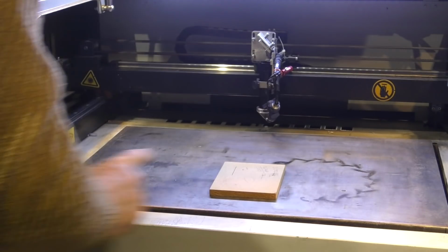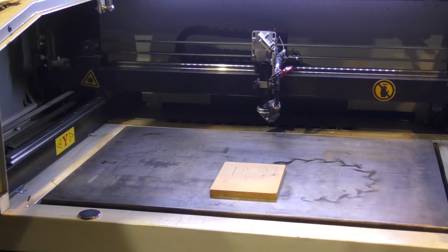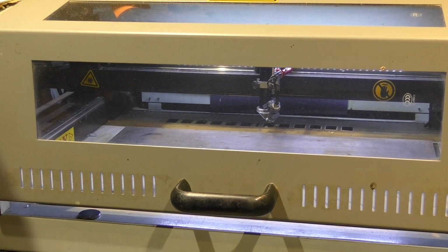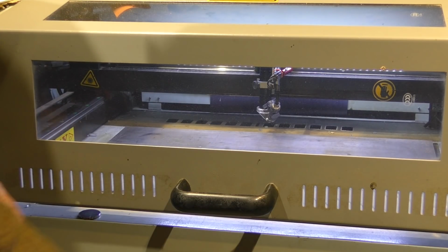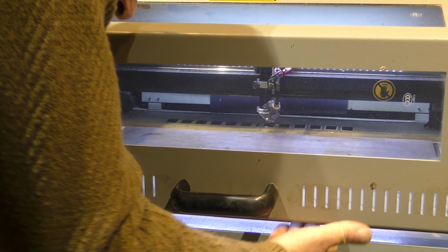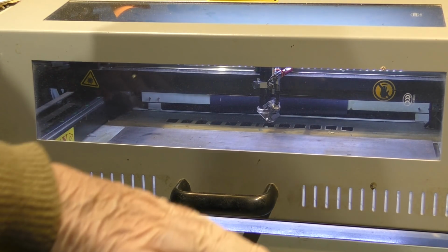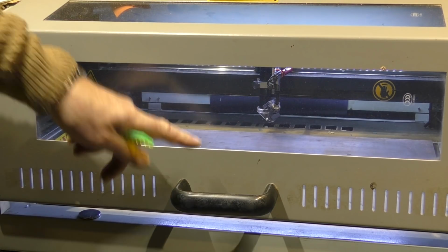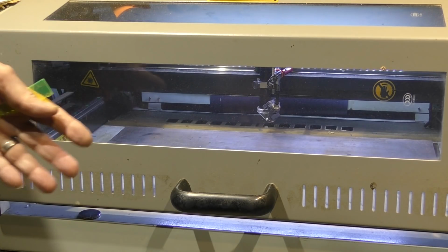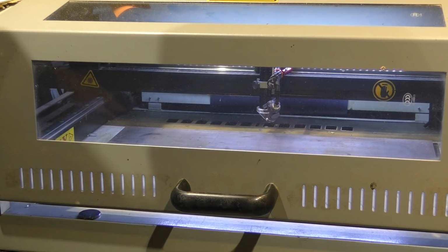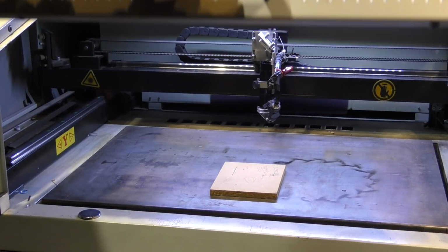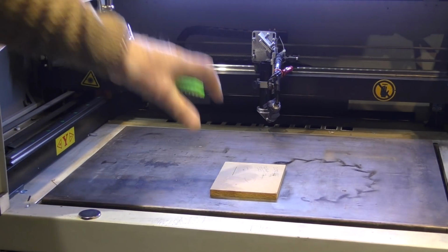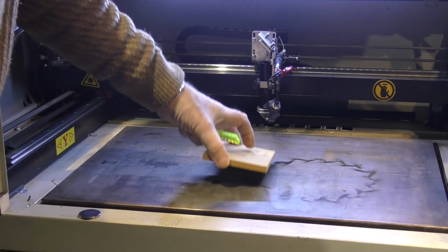You will notice on the corner of my door I've got stops. Although I've got some holes here which I've blocked off with tape, I want a sheet of air to be drawn in to my machine and pass rapidly across the engraving surface. If you're cutting, it really could do with going underneath the cut to extract the fumes just as quickly, because you saw yesterday what happens when the fumes condense on this surface.